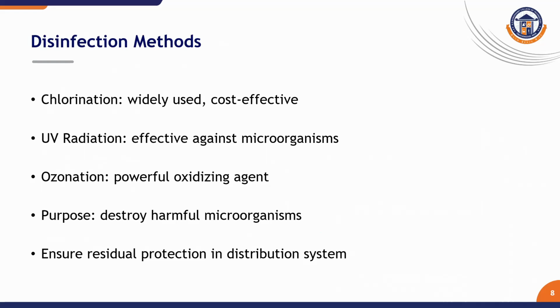Even after filtration, some microorganisms could survive. This is why disinfection is necessary. The chlorination is the most common method where chlorine gas or chlorine compounds are added to the water. Chlorine is inexpensive and provides residual protection, meaning it keeps working as the water travels through pipes to your home.